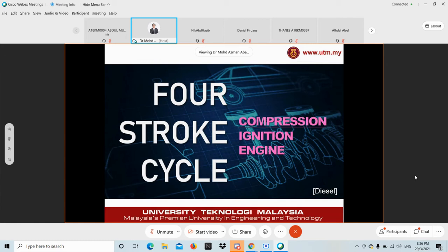Okay, kalau I nak cerita bab knocking ni 2-3 hari 3 malam tak habis. But knocking, if you drive modern cars nowadays, knocking still happens. Knocking still happens, okay? But you cannot hear it. That is one thing. Second, the engine management system or the ECU is clever enough to detect if there's any knocking, then what the EMS will do is they will try to retard your ignition timing.